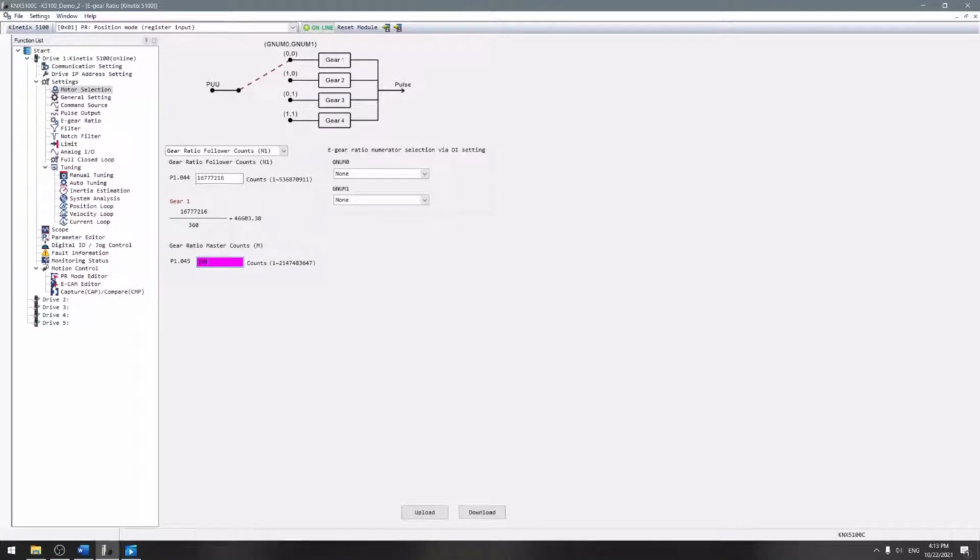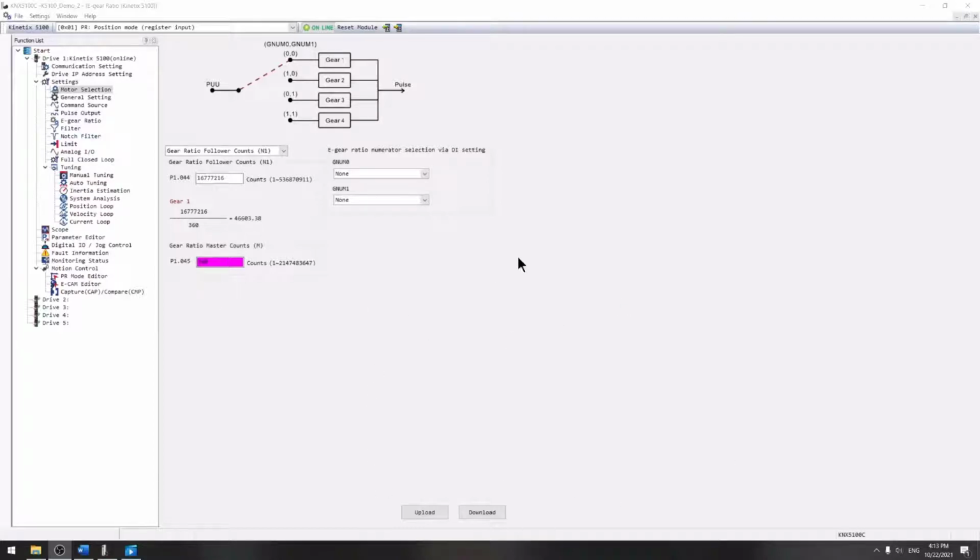In other words, if I command my motor to move to position 30, the motor will rotate 30 degrees. If I tell the motor to rotate 360, it will complete a full revolution. You can use the same logic to scale the counts based on your application, whether it's rotary or linear. Just make sure you're factoring in the reduction ratios present on your mechanical arrangement. In my case, my motor is directly coupled to this dial, so my ratio is 1:1, so I can use 360 degrees here.